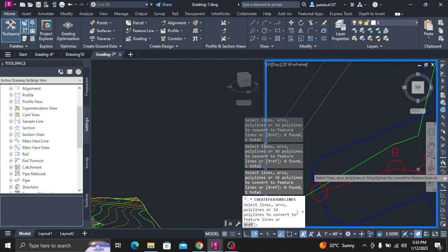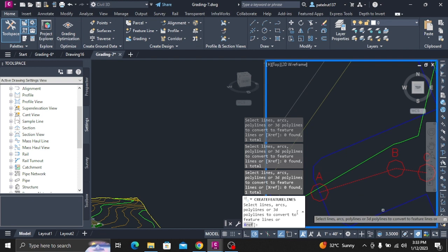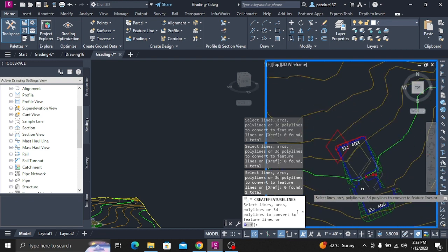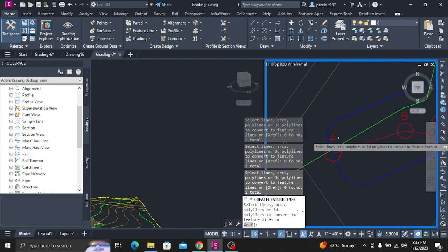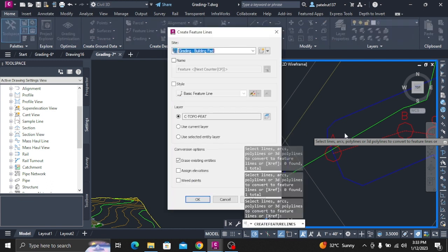Select Elevation Editor. In the Grading Elevation Editor, the icon indicates the point at which the feature line crosses the building pad. The white triangle indicates a split point, which is created when two feature lines cross at a location where neither one has a PI. Much like a shared vertex point, a split point acquires the elevation of the feature line that was most recently edited. If the other feature line has a different elevation, it gets a grade break at the crossing point.